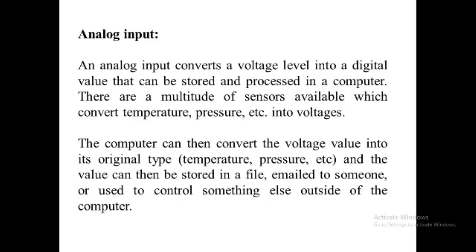Here we have to write a ladder logic program to read from analog devices, for example, a potentiometer. Also to write a ladder logic program to send analog signals to analog devices, for example, LEDs. And by using a library scale function to scale the value of the analog input.